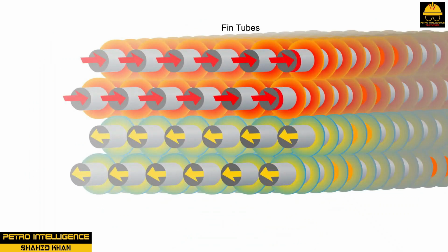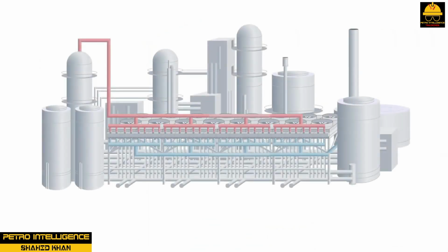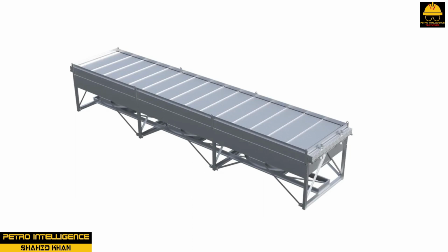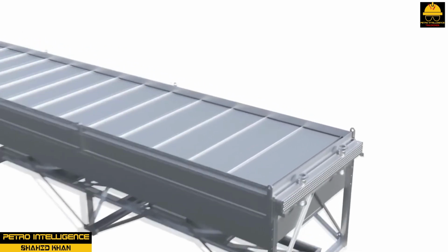Mechanical fans use a variety of drivers. Common drivers found in service with air-cooled heat exchangers include electric motor and reduction gears, steam turbine or gas engine, belt drives, and hydraulic motors.